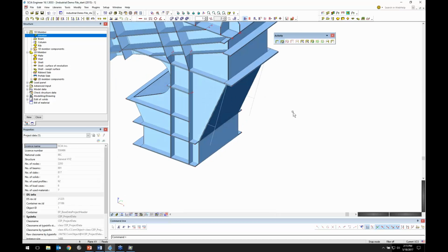So with the chute active, what we can do is we can modify the overall dimensions of this chute. So for instance, if I go ahead and select this particular node here, I can use some of the selection tools to say, hey, I want to select all other nodes that have that similar property. So I'm going to select the property here, and I'm going to use what we call the Select Elements by Property tool. I affectionately call it the lightning bolt tool.